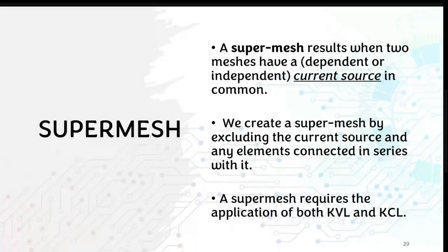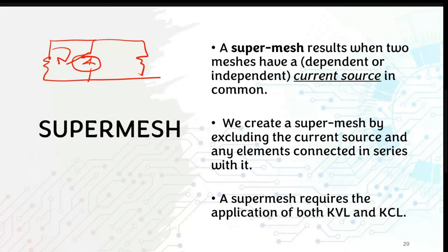All right. For mesh analysis, just like a supernode, we also have the supermesh. What does supermesh mean? A supermesh is when you have a current source in common, meaning you have loops sharing the same current source. For example, you have mesh I1 and mesh I2, and you have the current source here.